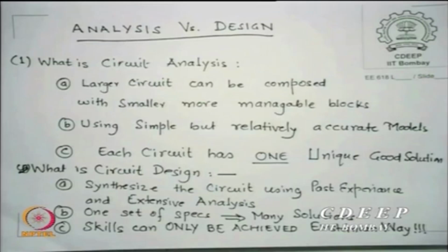You can solve it on a SPICE or a simulator, but normally when I analyze, I do not have such large papers to write such big expressions. So what I keep doing is use blocks, and see to it that the input and output always match. That is the trick we use, and always reduce into blocks and design it. And these blocks should be designed with very simple models for transistors or any other device we use. If they are too complicated, you cannot do circuit analysis easily.